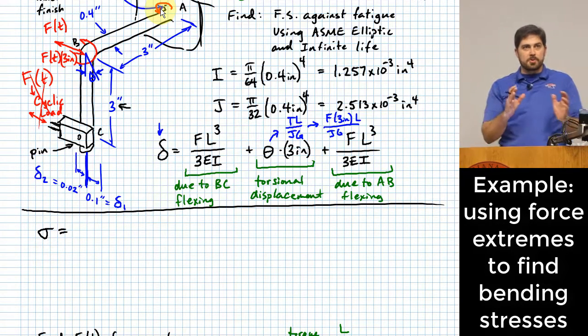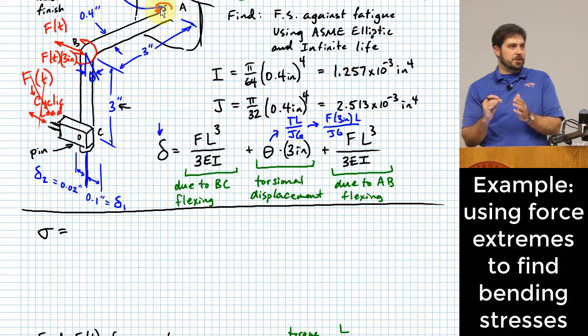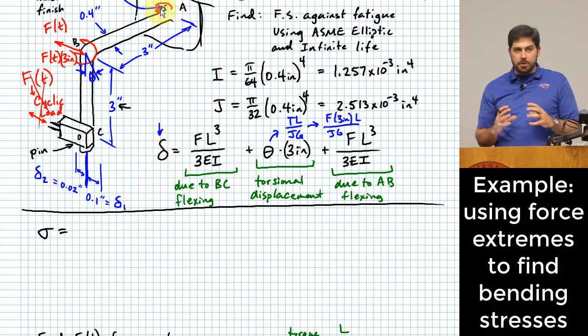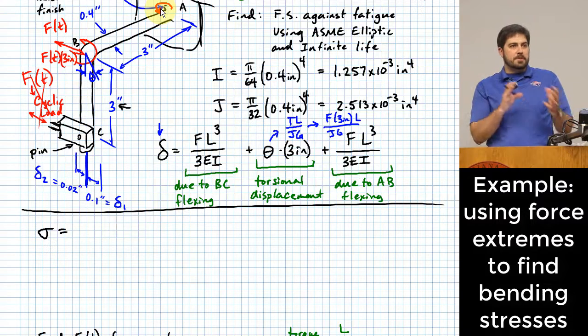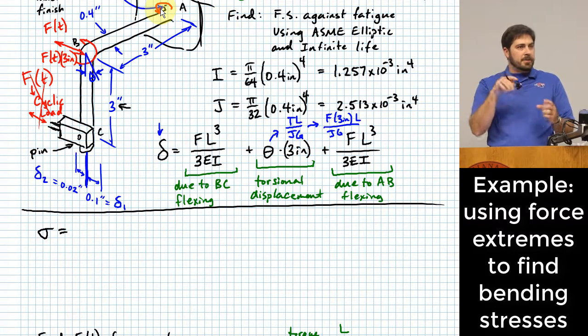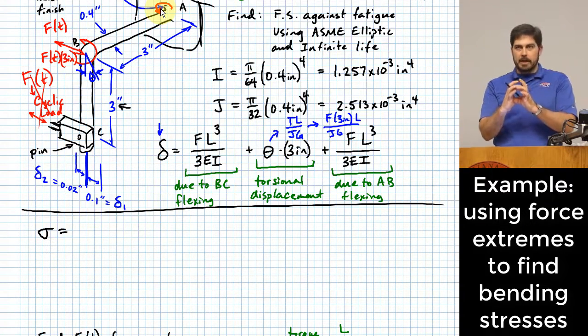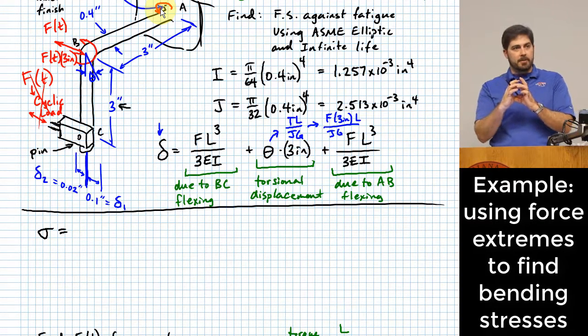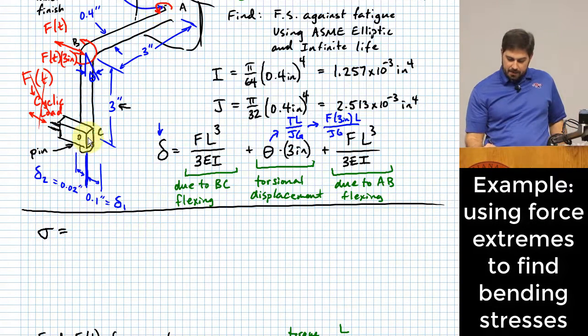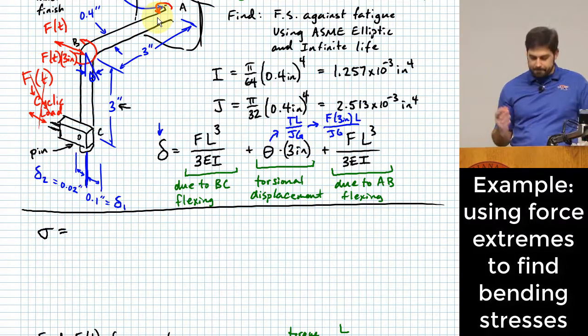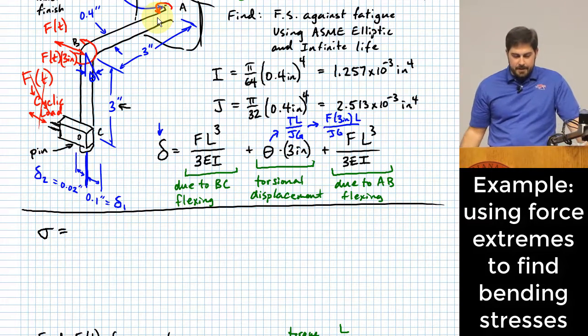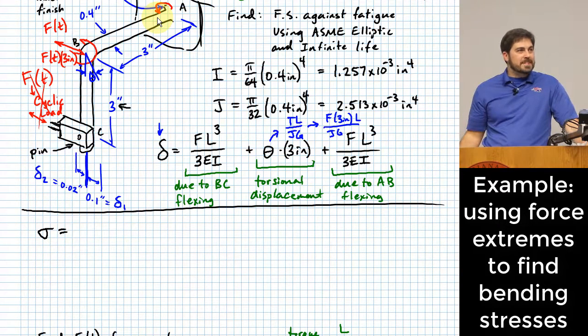That's where you have the worst amount of tension happening due to this flexure, right? As far as torsion, there's no one spot that's any worse than the others around the entire circumference as far as the torsional aspect. But for the flexure aspect, it's going to have its worst case stress when this thing is pushed to one side like that, and it'll be on that back side. That's not really part of our question that we need to answer per se, but it's always good to think about where this actual location of material is where we have our worst case.